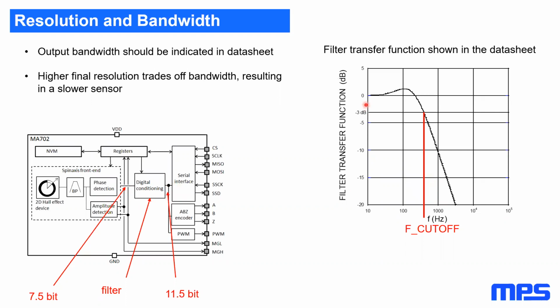Again, the trade-off is that we're going to get a cutoff frequency that's significantly lower than the cutoff frequency of this direct front end. Some of my very, very advanced customers that are doing robotics and higher, PhDs upon PhDs, ask us, hey, can you just turn this thing off completely and we'll do our own filter, because they want very specific trade-offs.